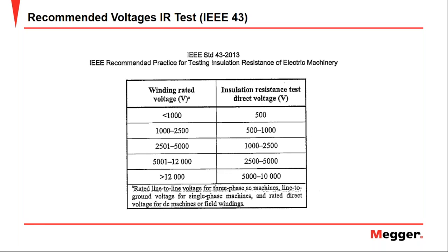Also we can do the measurement with a guard cable, and that is an option that we have to eliminate the contamination readings and only be focused on the leakage current that is going through the insulation. So depending on what you want, you can connect the cable as you want to do the test, and know if you want to do a very particular test.